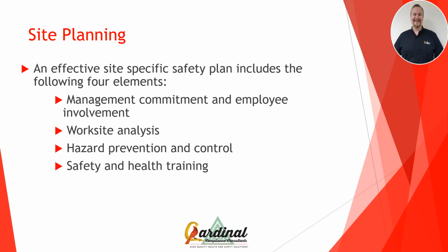And I've actually asked contractors that have worked for me in the past, okay, I see you doing this, you're waiting until 6 foot to use your fall protection, but in your site safety plan, you say 4 foot. Well, as the client, guess what I'm going to hold you to? I'm going to hold you to the contractual documents. And in our safety clause, it says we're going to follow either your policies and procedures, or we're going to follow mine, whichever is more stringent. I've had that happen where contractors didn't even realize what was in their own safety plan. And so that's why it's important.